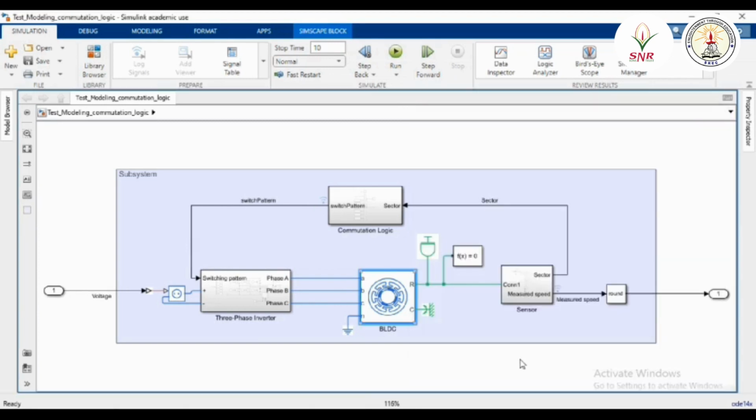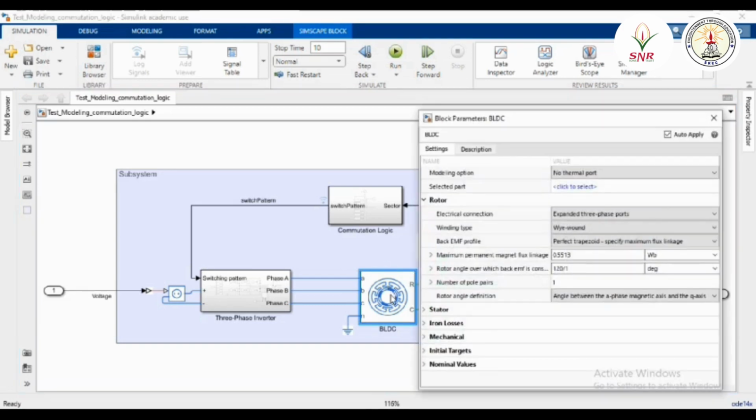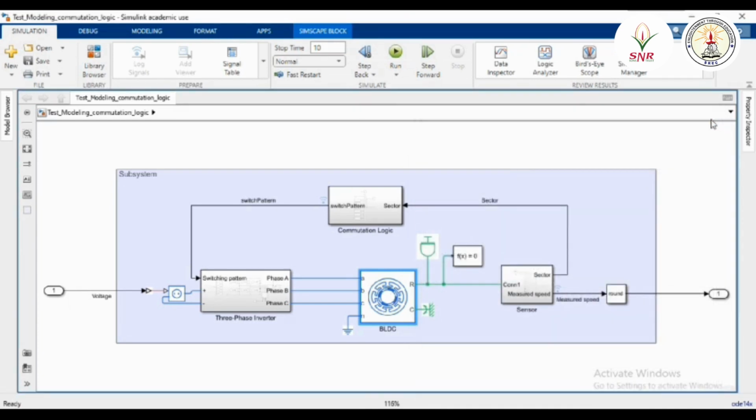Initially, we have three different conditions to be tested and checked before the model-based system engineering HIL test is considered. First, the hardware structure is to be considered before developing a model. The parameters of the model are to be fed to the software to test the basic functionalities. Here, parameters such as the back EMF and the RPM are tested in accordance with the acceleration. The output of the back EMF is considered.